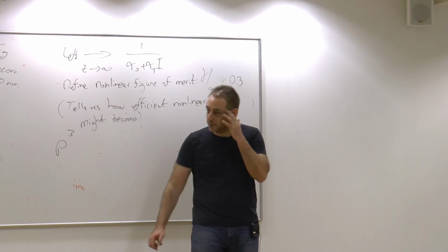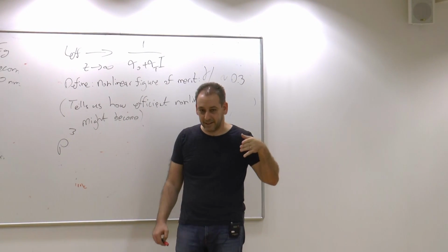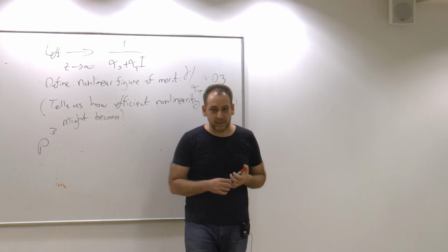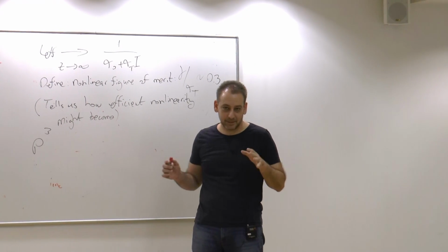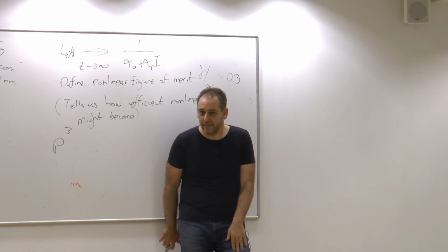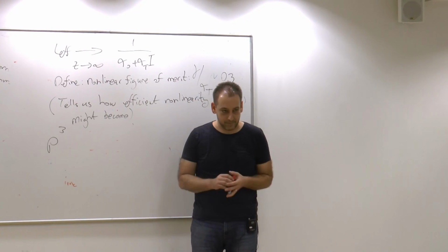The works that we've been doing over these last few years, when we define waveguides by a direct laser beam, it's two-photon absorption. A Ti:sapphire laser of 800 nanometers is perfectly transparent in the chalcogenide core layer. The only reason we see absorption and we see writing and lithography is TPA.